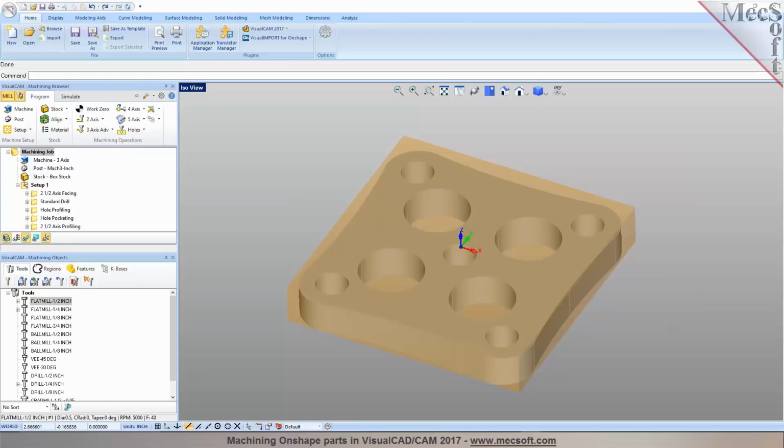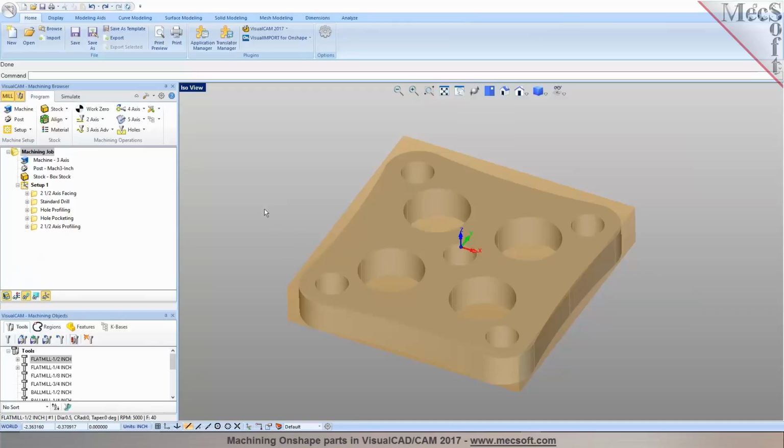Over on the left-hand side, you created a machine, I'm going to call it a tree for lack of knowing your terminology, where it center drills, drills, and grabs end mills, and then it cuts that part. Is there a way to save all those tool definitions and cut definitions, and then the next time I get a similar part, I can load that tree with the center drill and end mill and just substitute the new features into that template? Absolutely, yes.